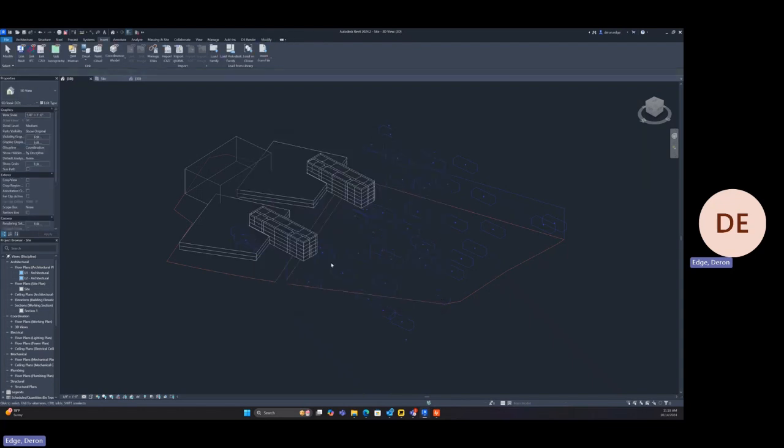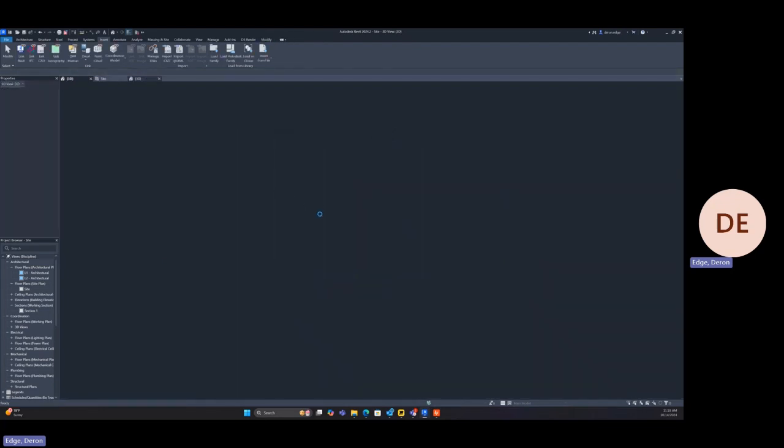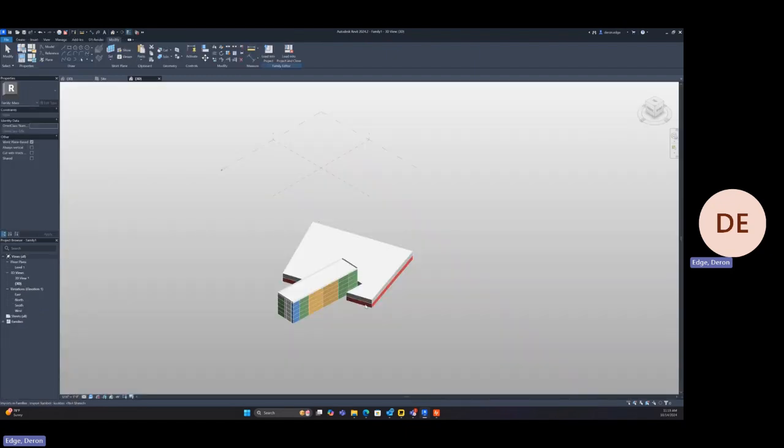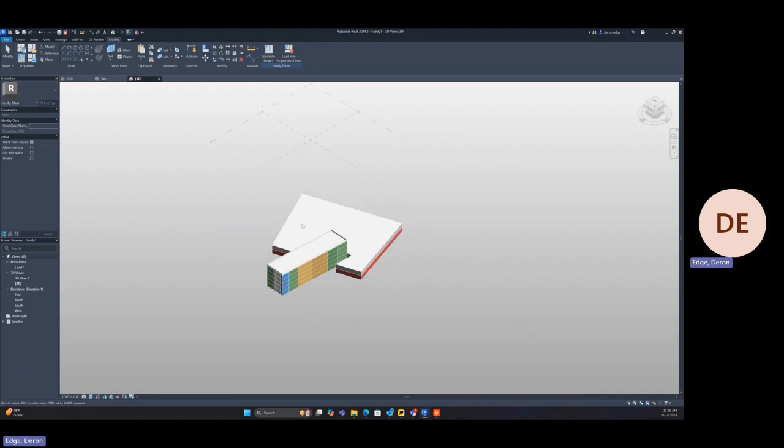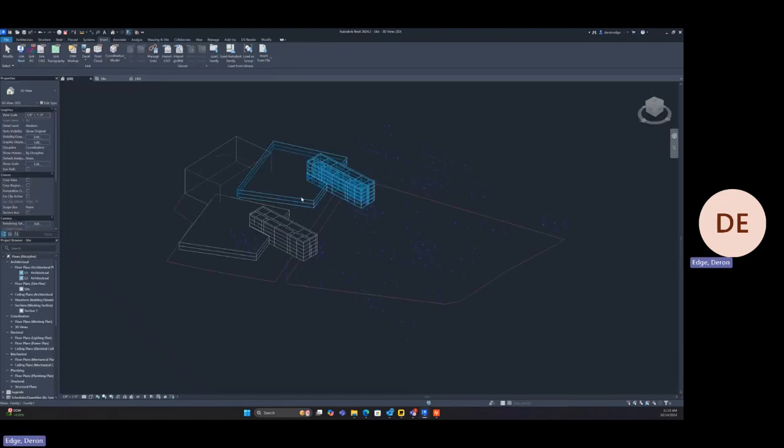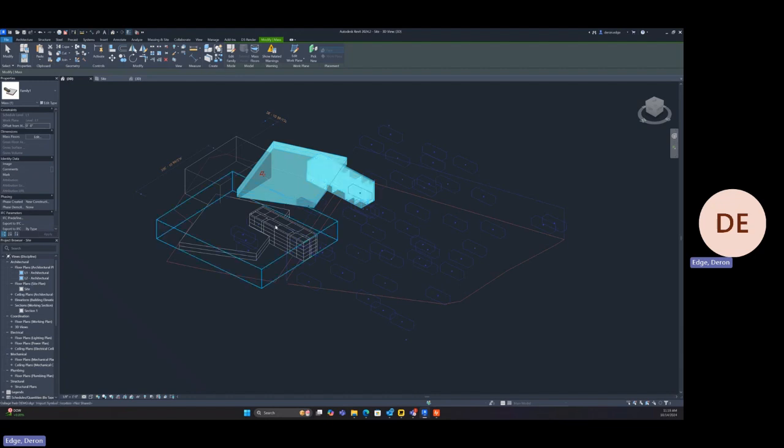What you had to actually do was create a 3D massing family. And inside the 3D massing family, what you did was import and link inside the SketchUp file, at which point this gets loaded back into the Revit site family, which is this character right here.